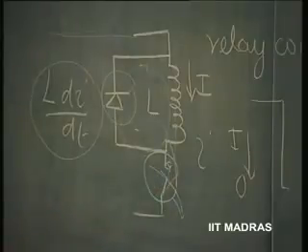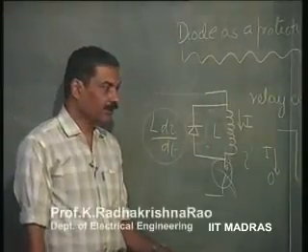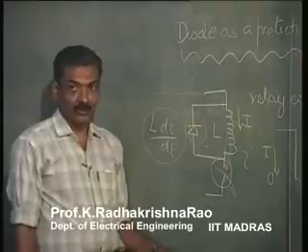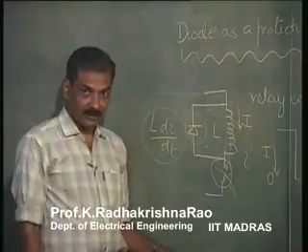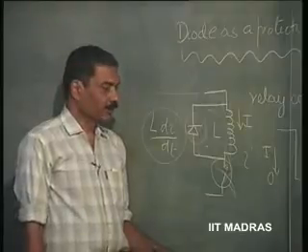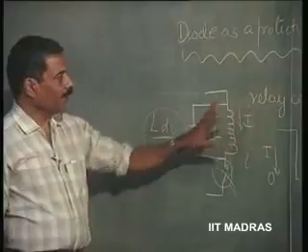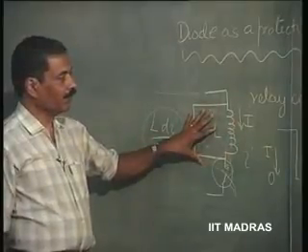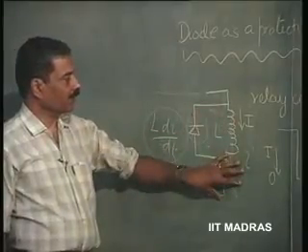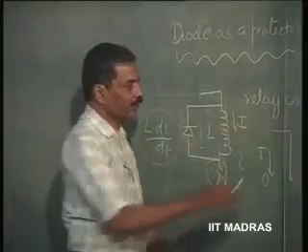So, this is a protective diode which is invariably introduced in almost all power circuits where there is an inductor and a steady current flowing through the circuit. This kind of application in a relay coil, to prevent the switch from getting damaged, is quite common in power electronics.